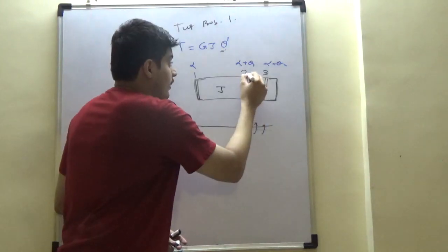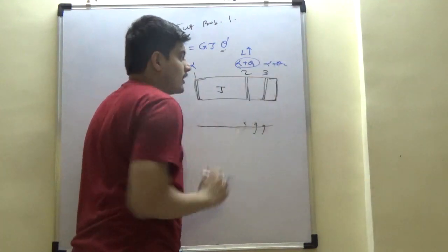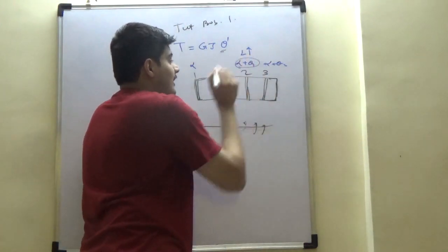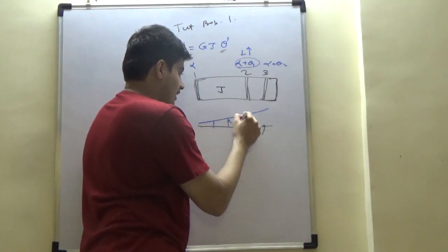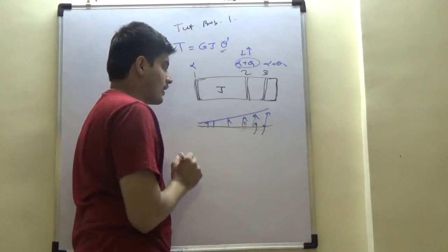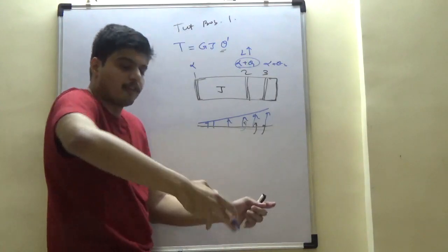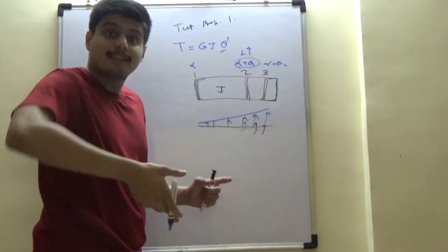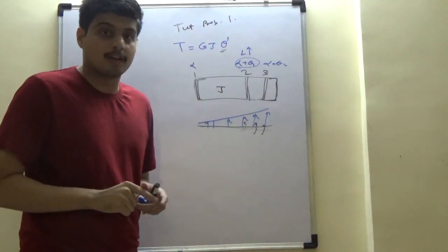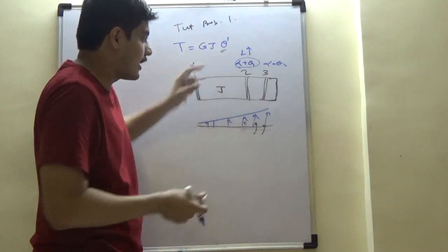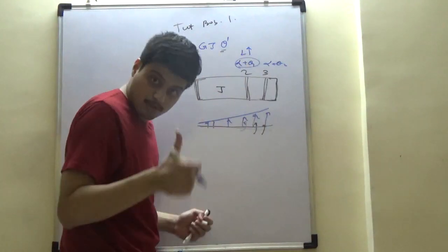That may be good or bad. If this increases, lift goes up. Right? Imagine these are small enough so that it is still not stalled. Then lift has gone up locally here, which means lift no longer is constant, but has suddenly gone up something like this. Added lift is going to create further moment, which may further twist it. So there is a coupling involved. This is called aeroelasticity, and that's the role of structures. So with this torsional theta dash, the twist that the wing brings in, the lift distribution becomes non-linear.